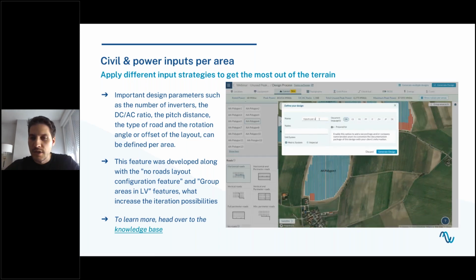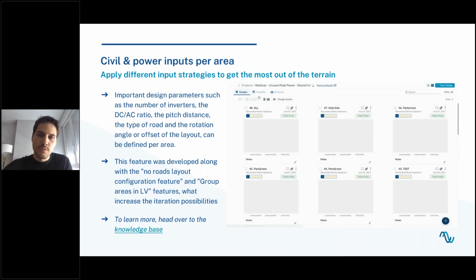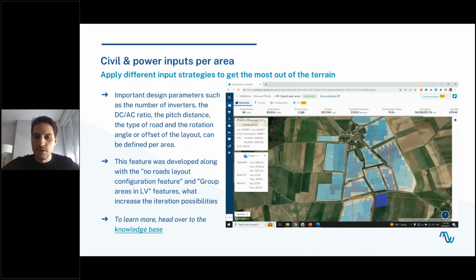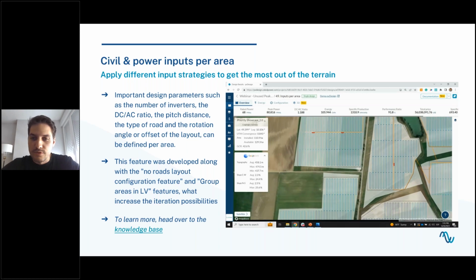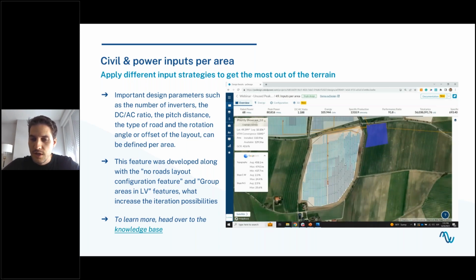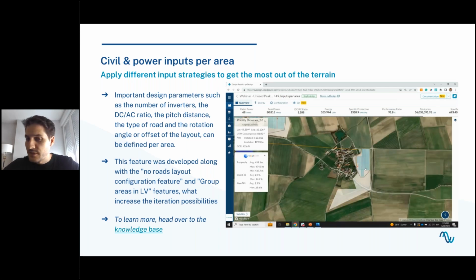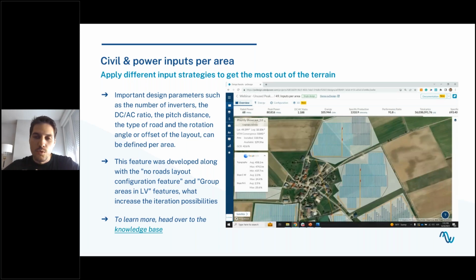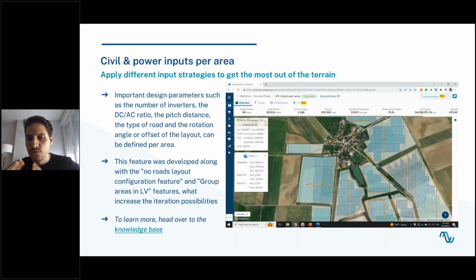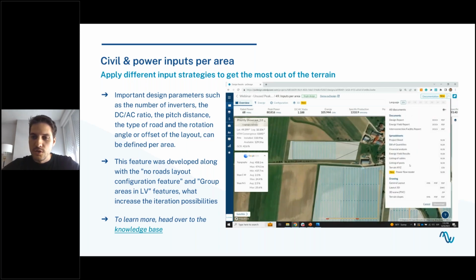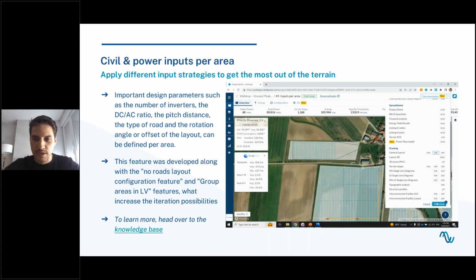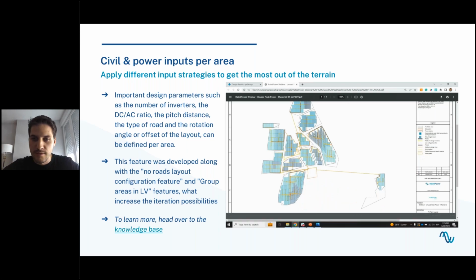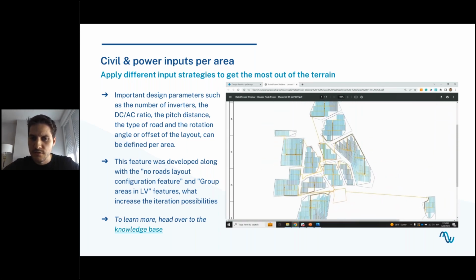And finally, if I generate the design, PV Design will generate all the documentation, and you will see the layout respecting your inputs. So vertical rows, horizontal rows, border adaptation, specific capacity in this area. More and more, this layout will be closer to what you can build. You can download the documentation, the general layout, and see the cabling, the position of the power station, the structures, etc.